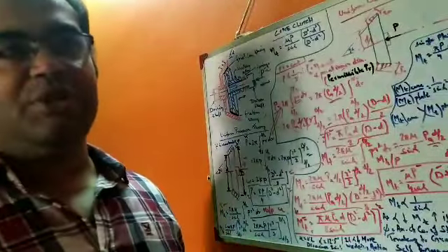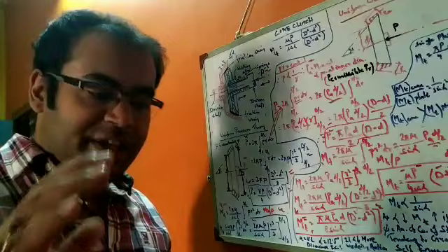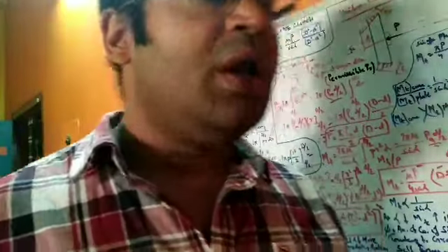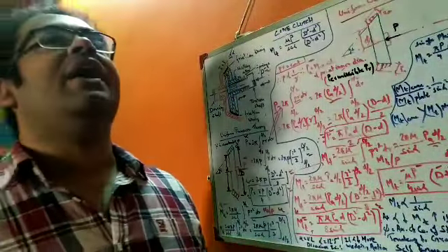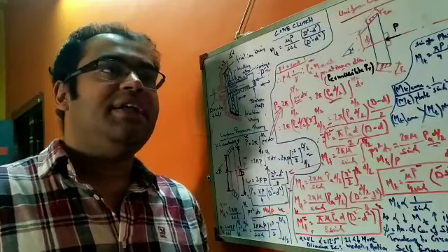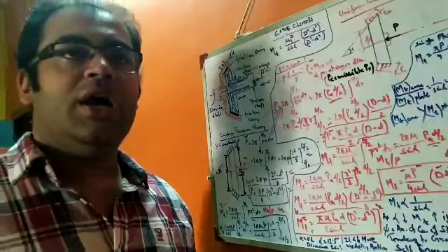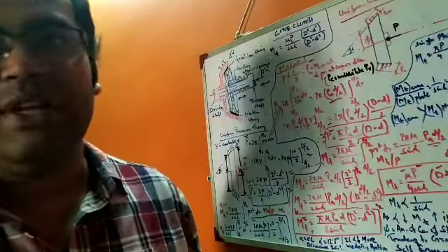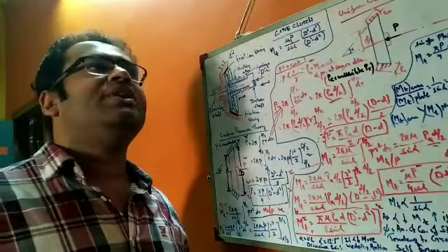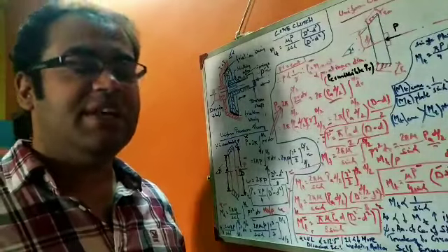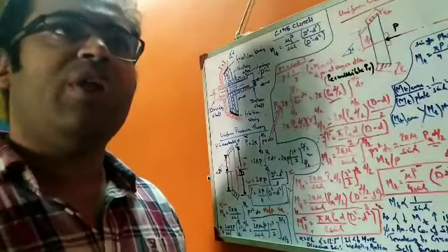But there is a limit. If you continually go on decreasing the value of alpha, it looks very interesting. We get more and more torque transmitting capacity. So with less applied force, we could get a greater amount of torque. Less applied force is required, and we are getting more torque.